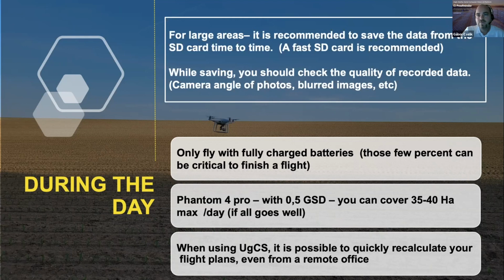While you are copying the files to your laptop, you can let your drone rest a little bit. You can leave it out in the open, let the wind cool it down a little bit. You can always check the props and the hull for damages, manually or visually check your drone if something is out of the ordinary, and you can use this time for these kinds of things.